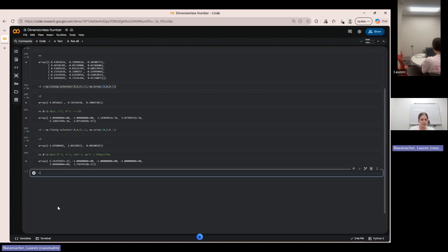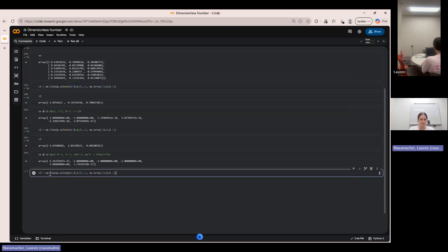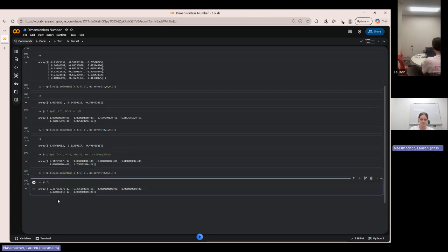And finally, our C3, it's going to be the last equation. Once again, it's going to be the exact same code, but we're going to change the 1 for the viscosity. Run that. Do the dot product with our null space and analyze. So our pi 3, we have that length and diameter are negligible, but velocity has the exponent of -2.